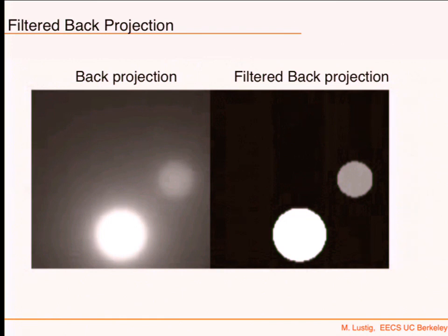In what domain? Like each projection really gives you a measurement in what domain? Through the Fourier slice theorem, in the frequency domain, right? Each projection gives me a line in the frequency domain. So you can think of it as sampling in the frequency domain.